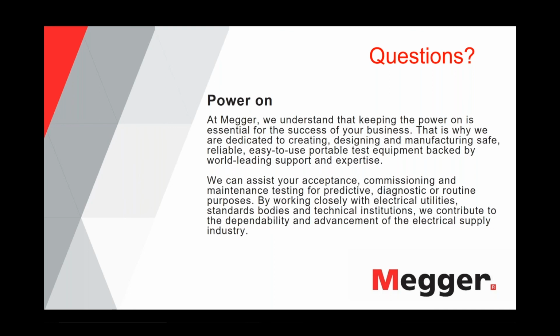Why does that make a difference? Because you measure dielectric properties, and you always have to measure dielectric properties between conductor and shield. So in the first case, when you have a belted cable, you can really not measure individual phases. You can measure the whole thing and see what the losses are, but you cannot measure the individual phase. Whereas in the second situation, where you have individual neutrals on each core or phase, you can do that.